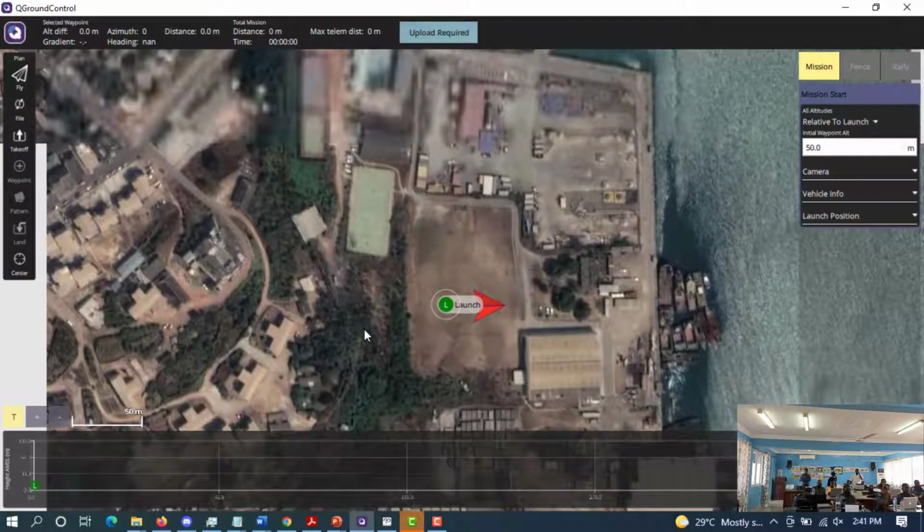They will not fully go off immediately. They will support it until the fixed wing momentum is fully established. Then our drone will climb up to this waypoint. Let's say this is waypoint 1. From 60 meters, my waypoint 1 will be maybe 90 meters.